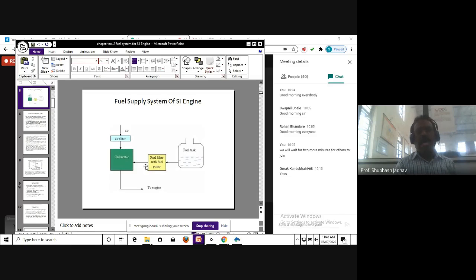After measuring the fuel and atomizing it, we have to take the air from here and then mixing has to be done over here. Why? Because we have to ensure that the fuel is distributed in the air in a uniform manner. Uniform mixing of the fuel particles in the air is very important, so that we can prepare a mixture of uniform strength.